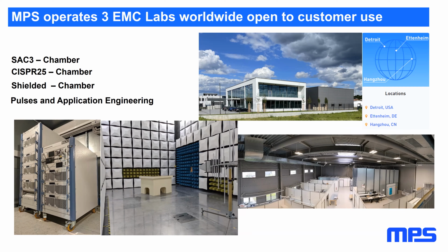Even if you have not a divider, but a time delay from one to the other, you could start with your master with the spread spectrum, and your slave would also be forced to run in spread spectrum. So in general, there's nothing wrong with running multi-phase systems with spread spectrum.